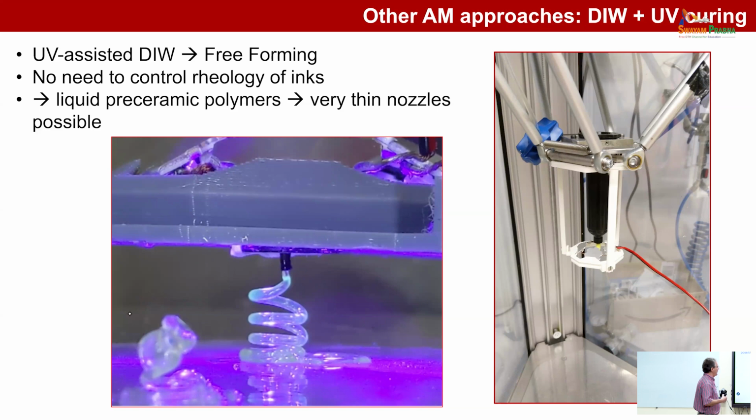By activating the curing, we can freeze the filament precisely and quickly in space, achieving structures that you wouldn't be able to generate using direct inking. If you use direct inking, it is basically impossible to have a rheology of your material that enables you to retain that type of structure. But with almost instantaneous UV curing, you can do that.